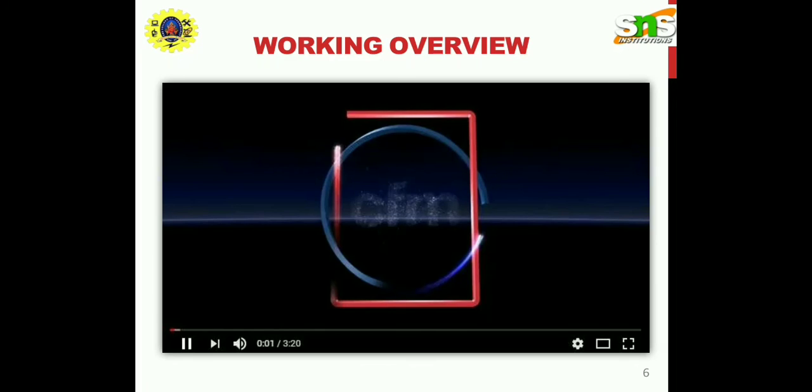The working overview of turbo machines is represented in this diagram. Any device that extracts energy from or imparts energy to continuously moving steam or fluid can be called a turbo machine. Elaborating, a turbo machine is a power or head generating machine which employs the dynamic action of a rotating element.